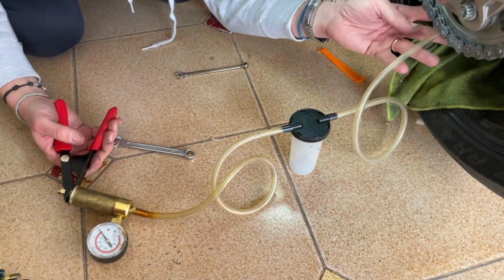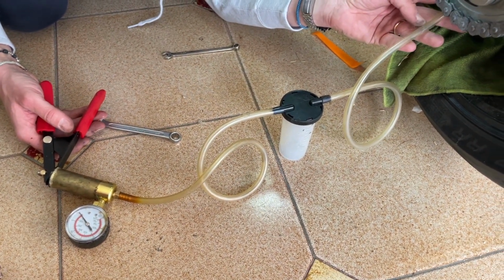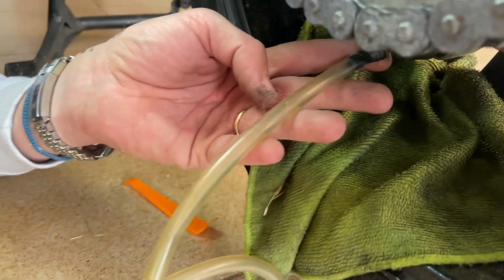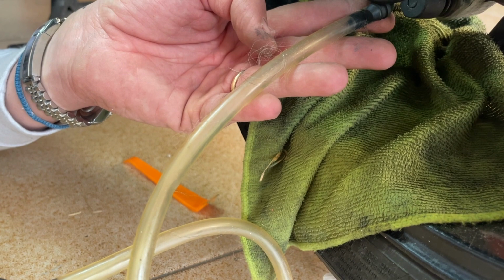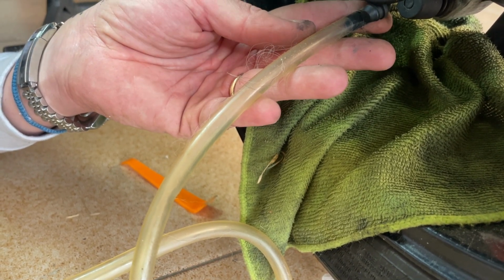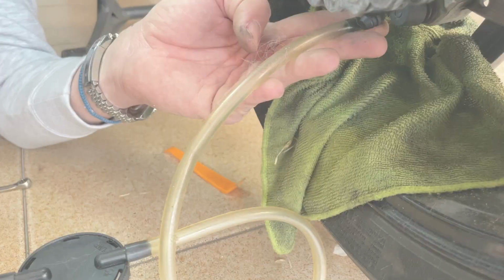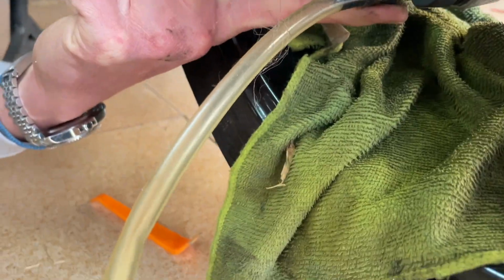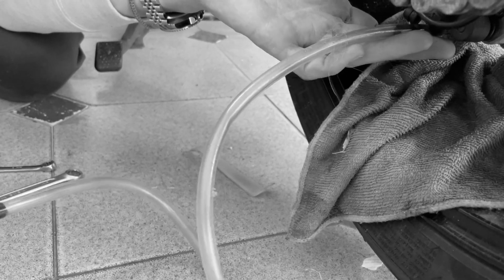and we will pump out, and we are expecting oil with air bubbles to come out in the pipe. We have to continue to bleed and at the same time make sure that we are not running out of oil in the reserve tank, and we have to bleed till we don't see any more bubbles coming out. There is really a huge amount of air in the circuit. Now I understood why I wasn't able to brake.